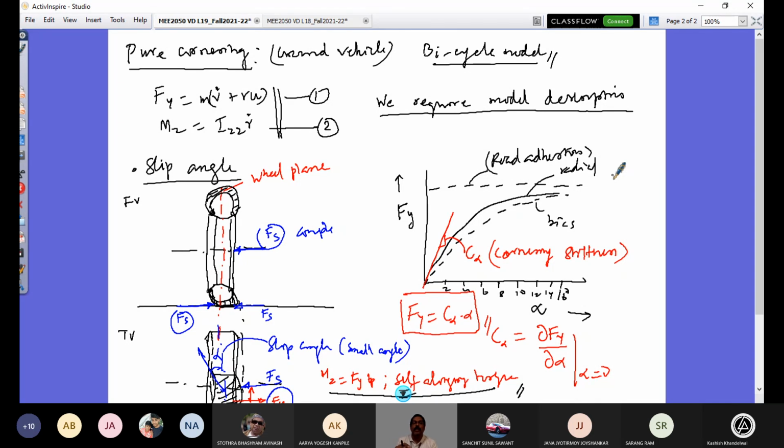There are two with respect to the geometrical aspect of your vehicle: symmetricity, principal axis, and so on. Another thing is the necessary elimination of degrees of freedom. In a ground vehicle, heave motion and pitch motion can be eliminated first, and then you can also eliminate your roll motion as you look at only directional control and stability in the yaw plane.